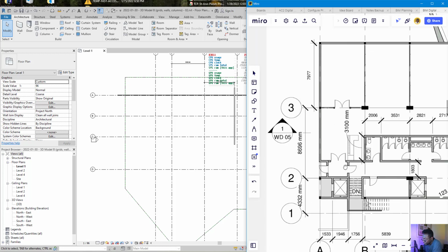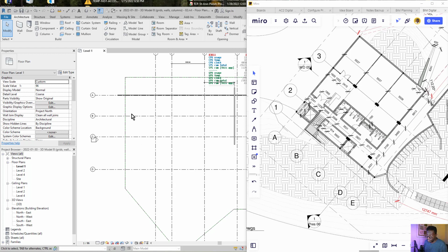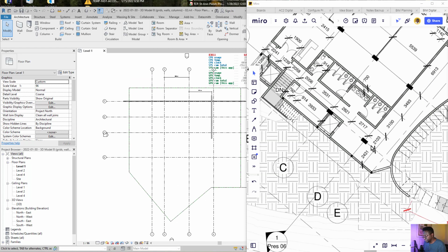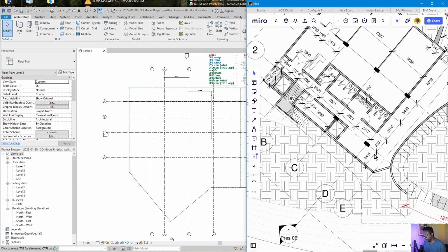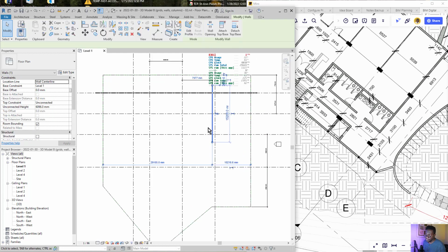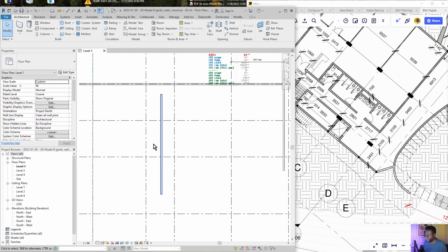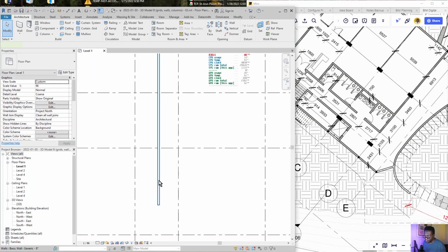Then we need to now add in this outer wall, which is here. All right, so that wall, which is here, and we can see that it is that distance away from grid line 2. So what I'm gonna do, you might draw this different ways, I like to copy my walls and just drop them in the general location and then try and tie my dimensions together.